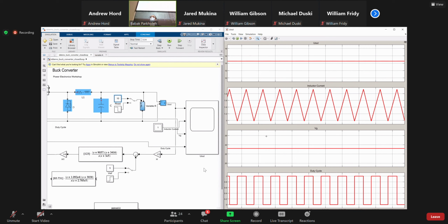Right? Do you agree? So what you see here is by changing the load, the average current changes, but the ripple doesn't. So that's an important fact. So the load doesn't affect your ripple. So the design of a converter is not dependent on the load when you want to pick an inductor.